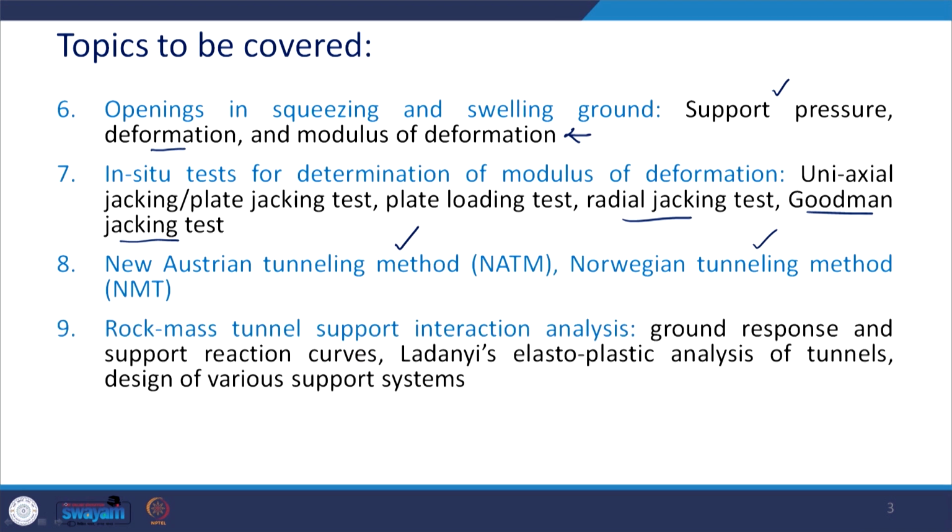After we get this much of the foundation related to underground space technology or the design of underground excavations, then we will take up the topic which deals with the rock mass tunnel support interaction analysis, and in this one we will first discuss the phenomena of this interaction. In this context, we will learn about the ground response and support reaction curves, and then we will go ahead with the elastoplastic analysis of tunnels considering this interaction, and this is called Ladanyi's elastoplastic analysis.